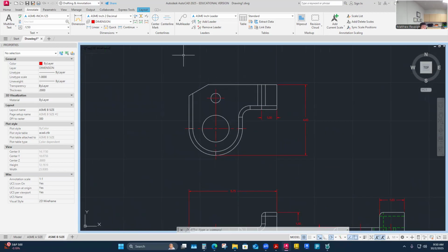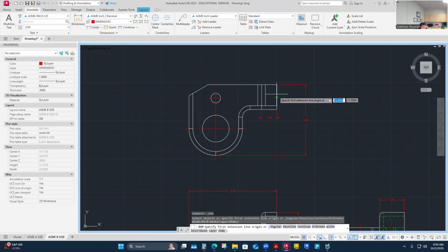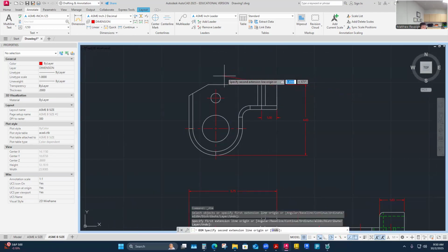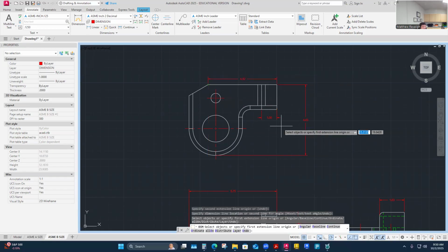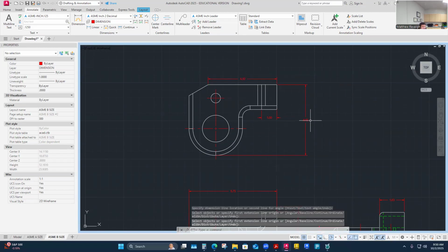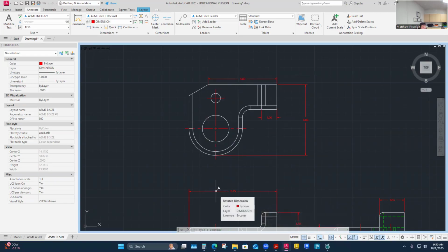So I think for this, this right side surface is definitely a datum. I feel like this is a great dimension to pull. It doesn't go in between the views because I'd have to go clear across and make a mess. So this is a good option for this outlier that breaks the rule of not being in between the views, but it's definitely showing it in the most clear position rather than causing a bunch of extension line woes. I'd be reaching clear across everything to that point, and maybe that's just unnecessary. So I've got that.